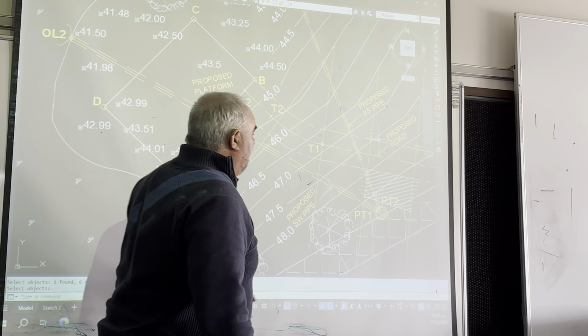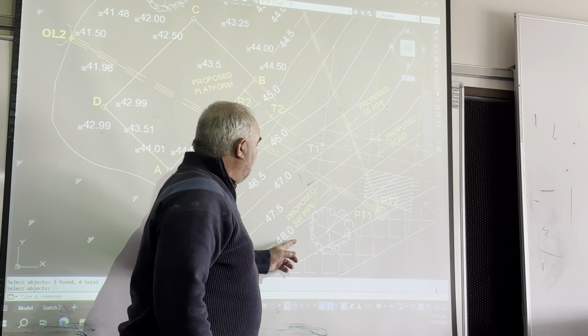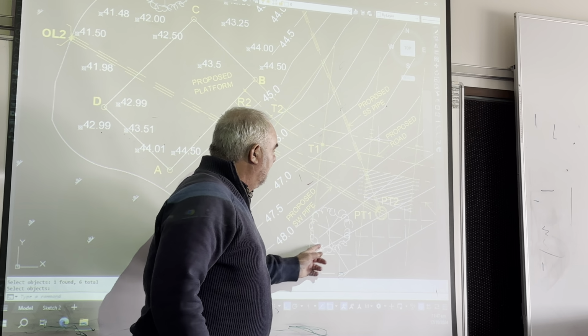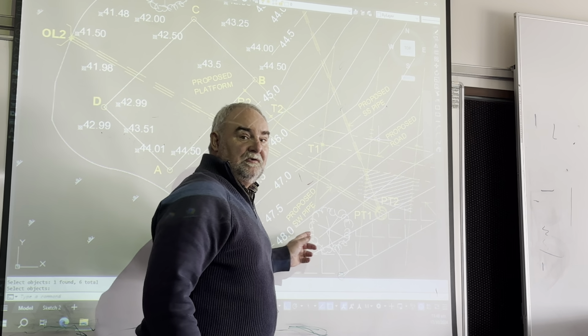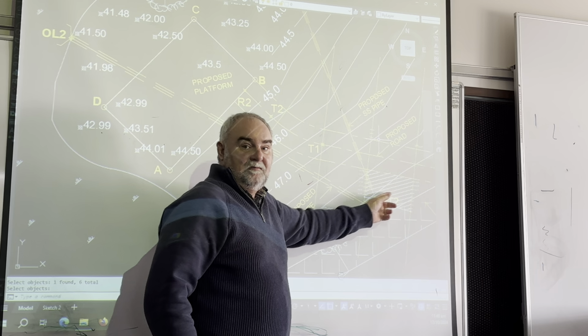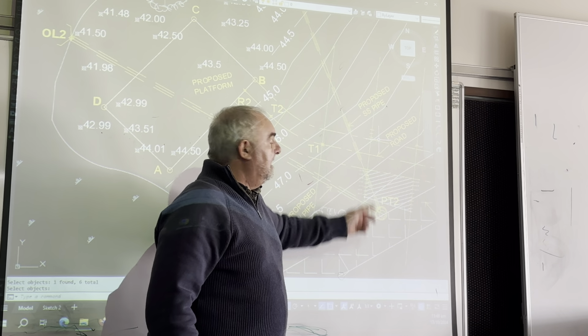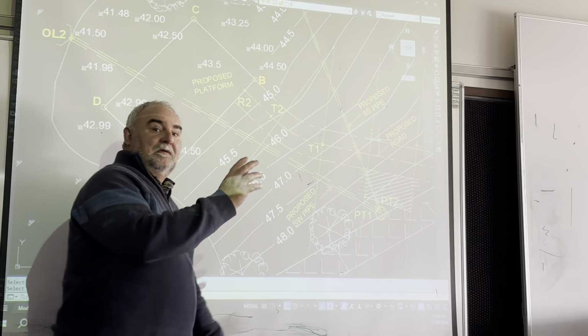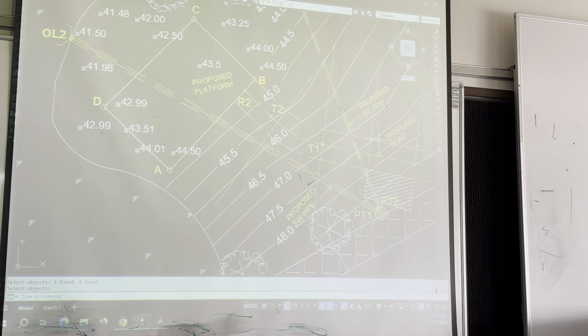Remember, we're doing every 0.25, so you do need to draw in here some 0.25 contours to match into them. Okay, more marks are allocated to this part of the assignment, but if you don't feel that you want to have a go at this, then that's fine.